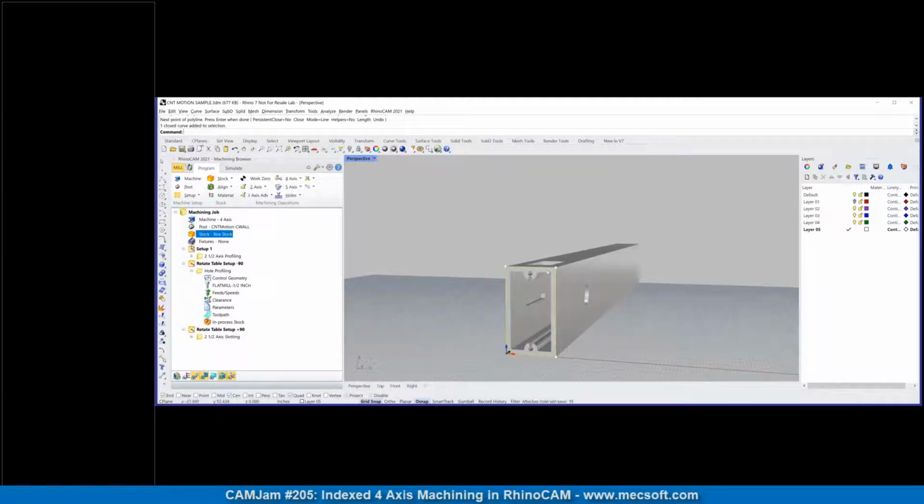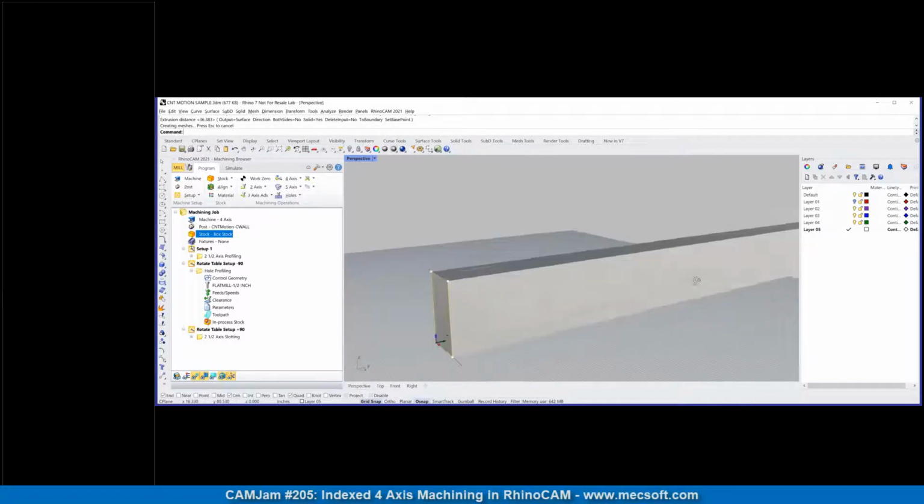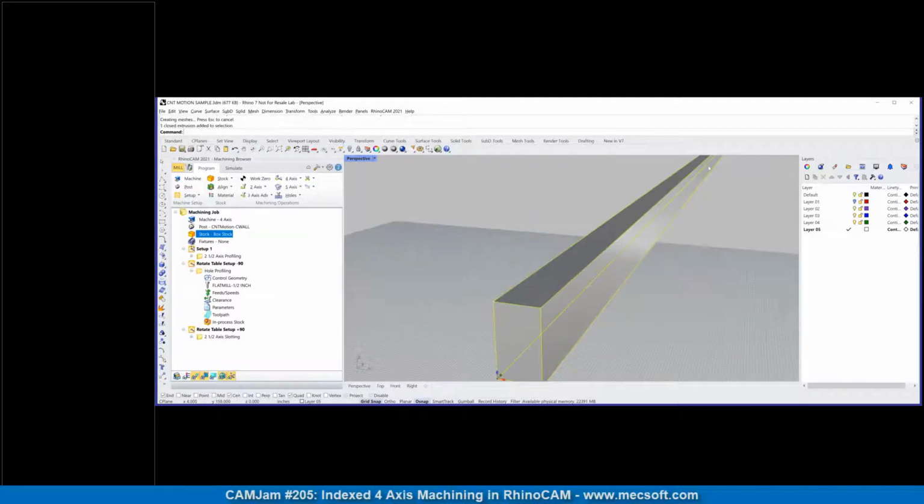So, okay, if you have the outline like that, just go to solid here, and then extrude planar curve straight, and then you can just do that. That's how you do the solid. Very simple. That's exactly what I was looking for. Okay.